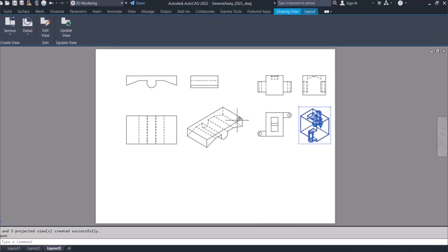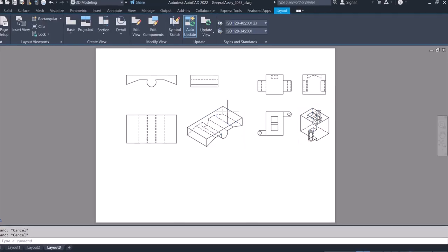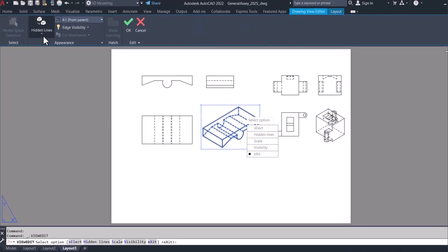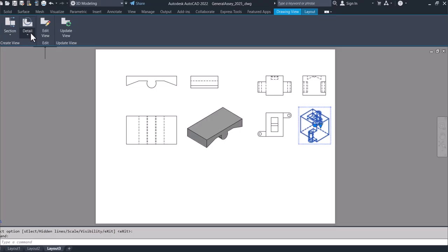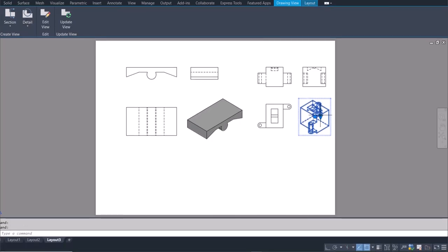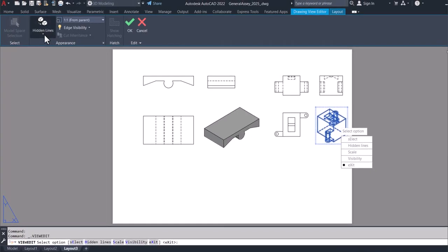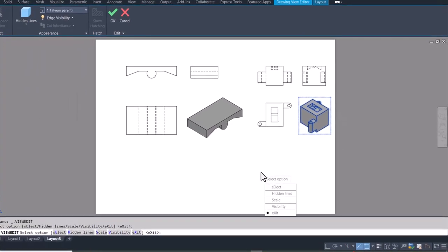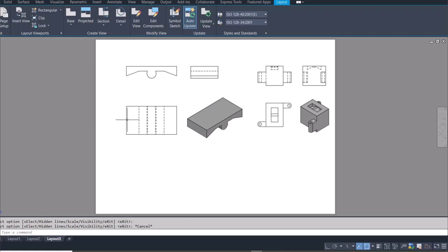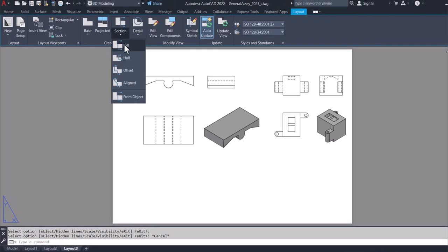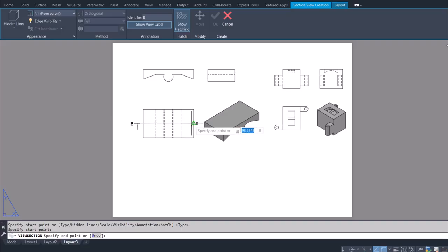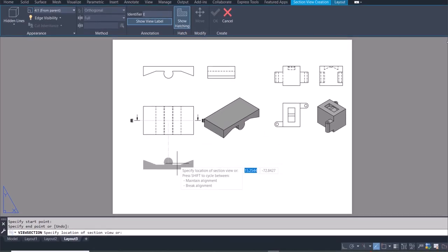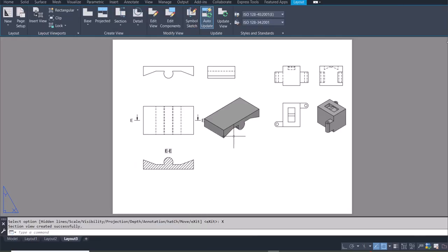So you see that by going through the 3D process, I am able to solve lots of the questions in only one go, right? So it might take you a while before you'll be able to model all of them and then assemble together. But the moment you are able to do that, now it becomes easy from there. So if you want to cut a section view through any of them, let's say full section of this one, then maybe through the center you can cut here, then maybe cut there and put it here as your section view, right? Which is easy.